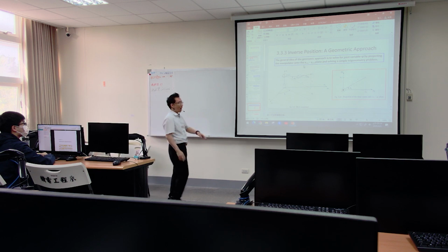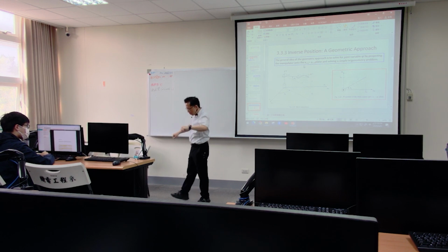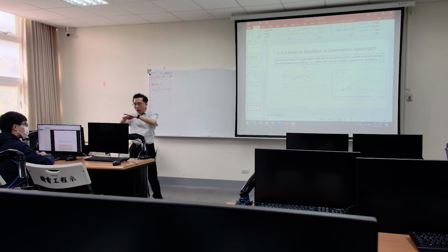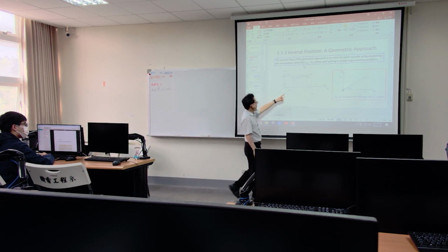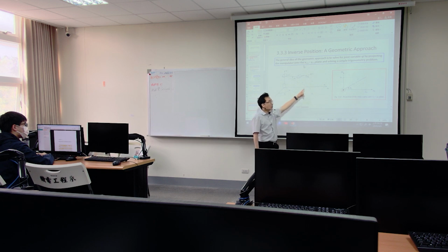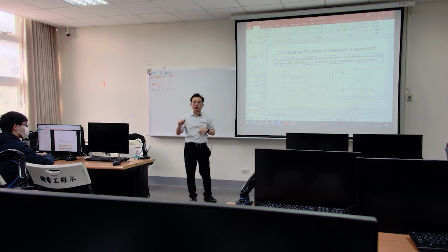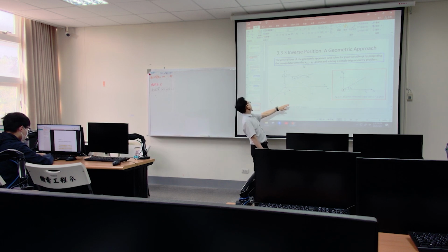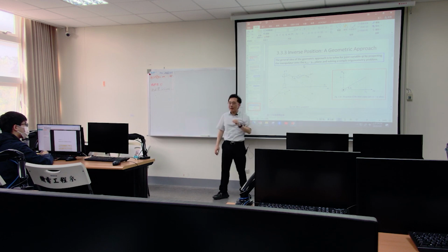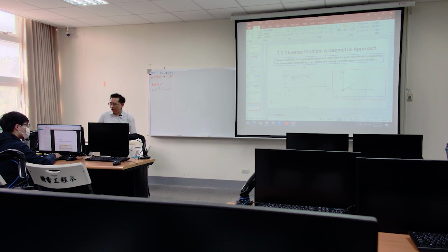Then we apply this geometry. So when you use the projection, you project onto your floor plane. Then you can have an angle, because you have an xc. In this spatial position, which is not called position but posture, you can project onto the xy plane. Then you can obtain the xc and yc immediately. Then you can find out theta 1.